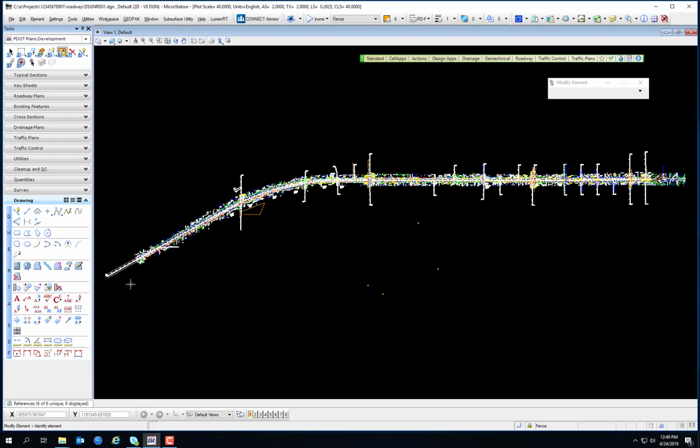So a word about placing elements. The objects drawn or placed in a model, lines, polygons, circles, text, etc., are called elements. Each element has several attributes that define the element, as we've mentioned before: the level, color, line weight, line style, fill color for closed elements, class, whether it's primary or construction, transparency, if it's transparent or opaque, or how transparent, and priority, which applies only to 2D elements as really just a display setting.